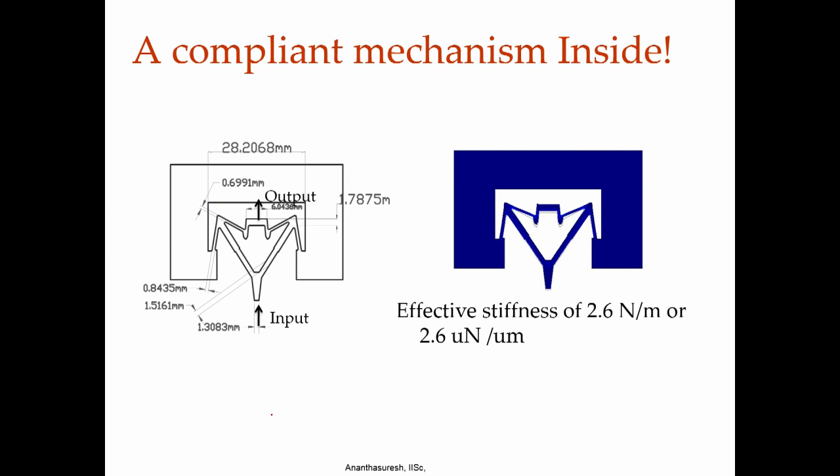So, what is important here is the compliant mechanism that is inside this force sensor. There is nothing else. You can dip it in water, you can put whatever fields, it does not really matter, and you can actually use this to measure forces that are applied on cells or other biological things where the environment may not be suitable for other types of sensors. They may be very expensive, but here the expensive part is a digital camera, which you can also get for 5,000, 6,000 rupees these days, and they are certainly cheaper than some of the smartphones you have, and after that it is just the compliant mechanism, our DACM.